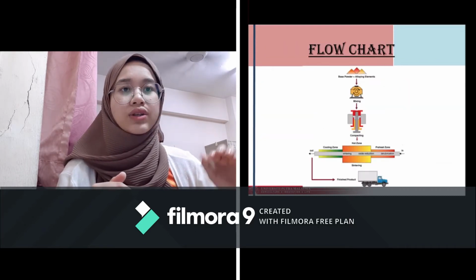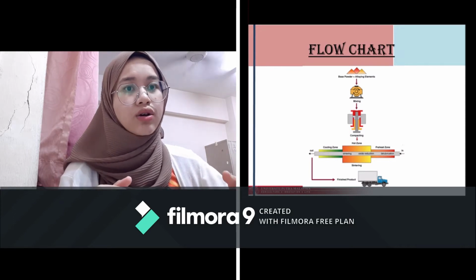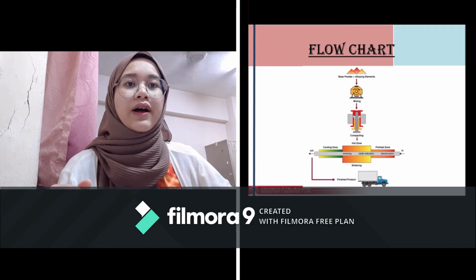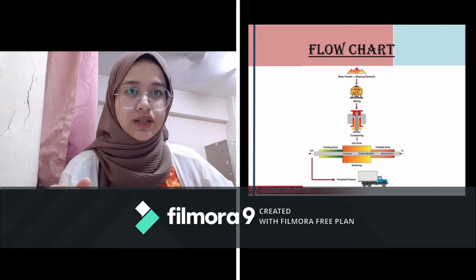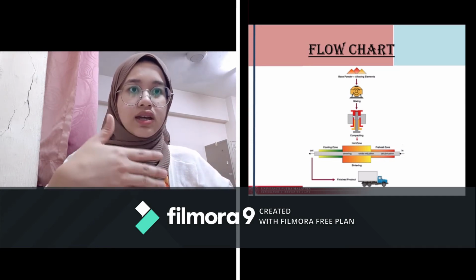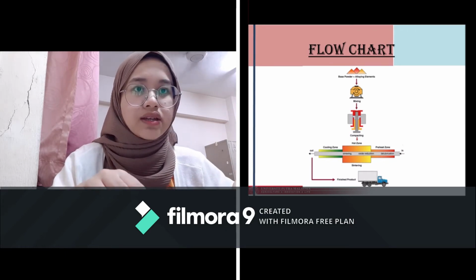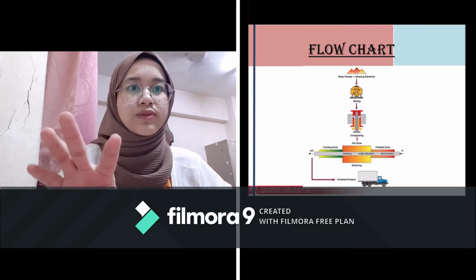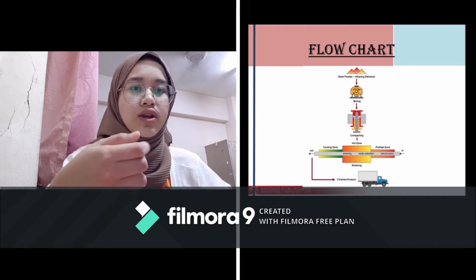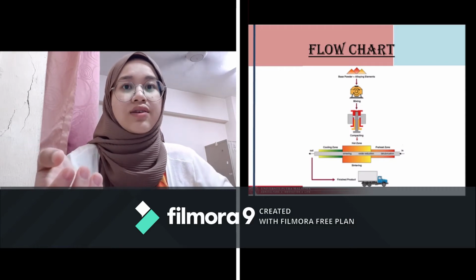Okay, before we go deeper into the powder metallurgy method for this car door production, this is the flow chart of the car door using a powder metallurgy method. First of all, we mix all the powder in the specified machine, and then we compact, and then we sinter in 3 zones, which are the preheat zone, hot zone, and cooling zone, and we go through the secondary operation or finishing operation, and then the car door is finished.